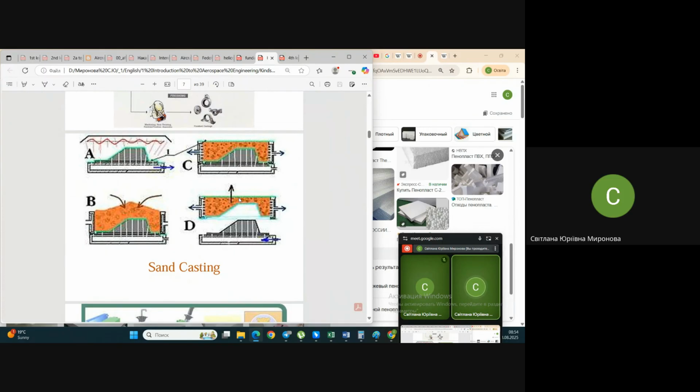They try to evacuate themselves from the mold that is poured with liquid metal. Usually they have a different gasification temperature than the metal that is poured inside. And that is why they start to move first. Quite clear that they are trying to leave the mold, while the other material, after contact with the cold mold, has already started to solidify.